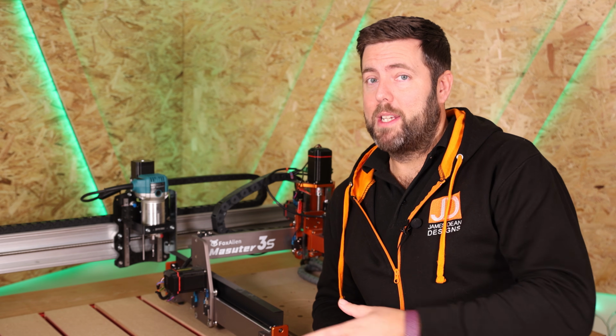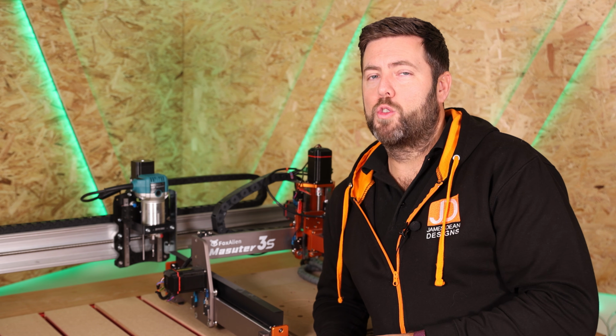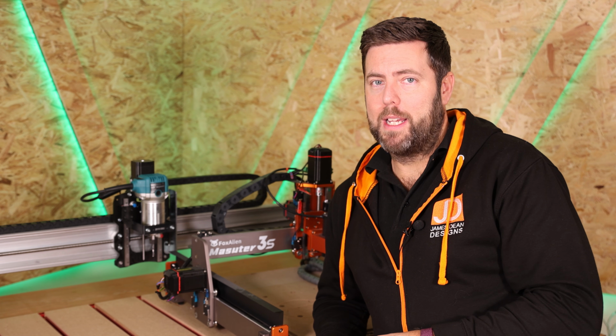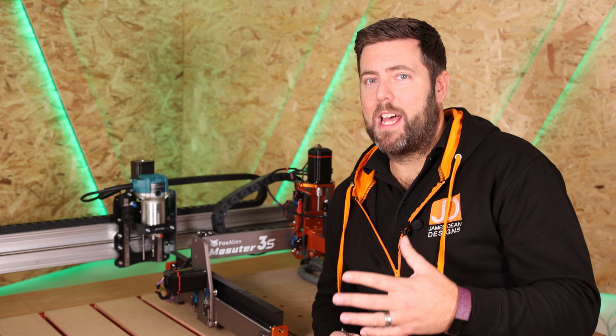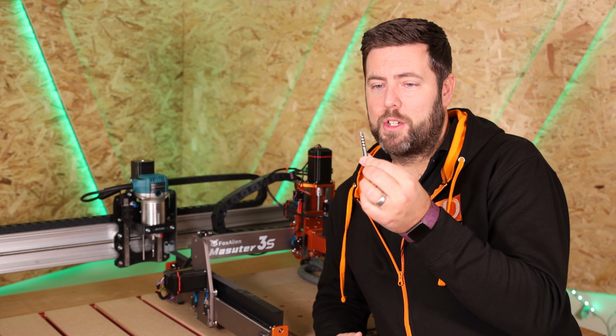Now you put that same bit into one of these machines and you've got to drop that depth of cut drastically, probably to only the thickness of the bit or a couple of millimeters deep. And that is ultimately, as I say, because of the limitations of the machine, not necessarily the limitations of the bit itself. Now I am very conscious that I've mentioned what feed is, basically the physical rate your bit is being pushed through the material by the machine.